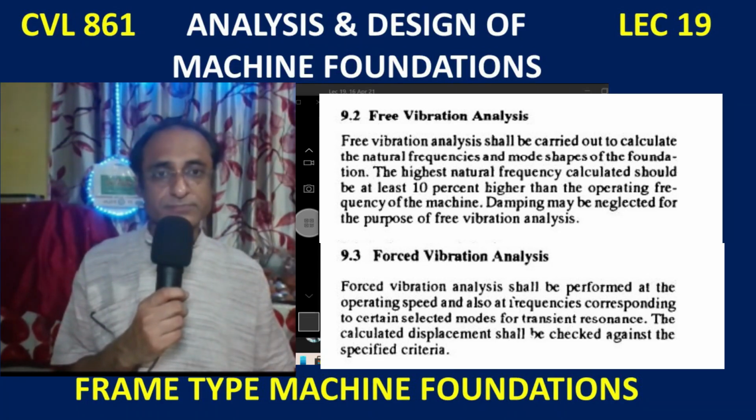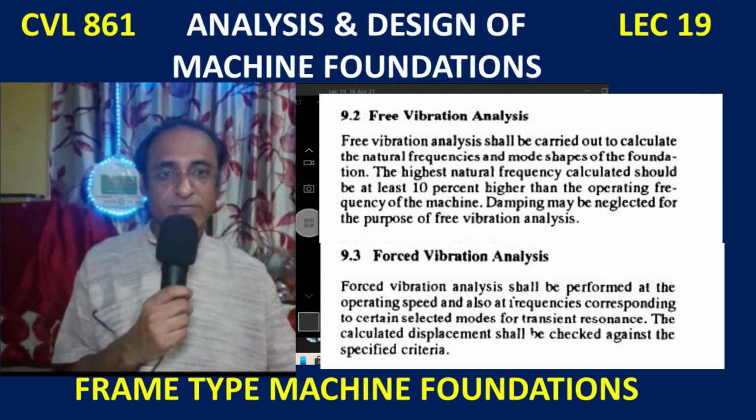So the code says that free vibration analysis shall be carried out to calculate the natural frequencies and mode shapes of the foundation. The highest natural frequency calculated should be at least 10% higher than the operating frequency of the machine. Damping may be neglected for the purpose of vibration analysis. Okay.